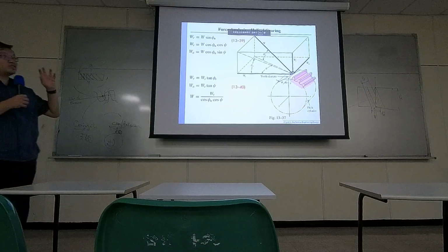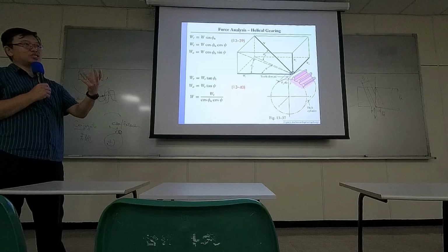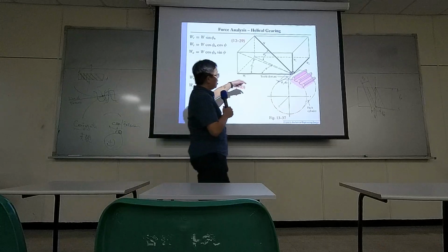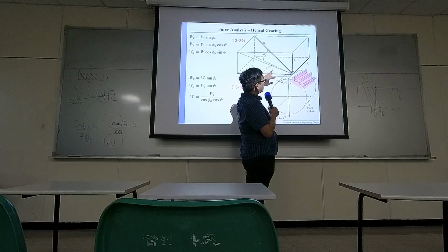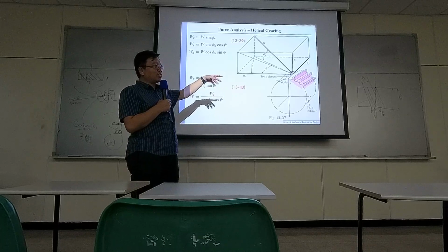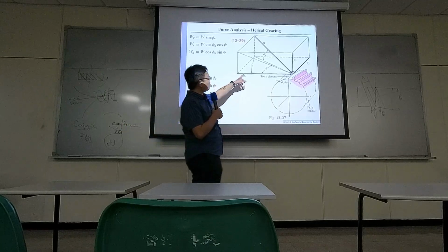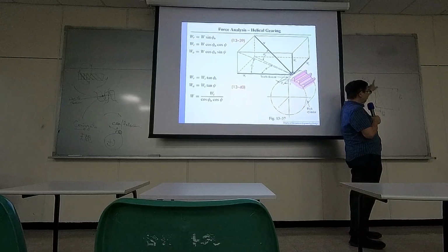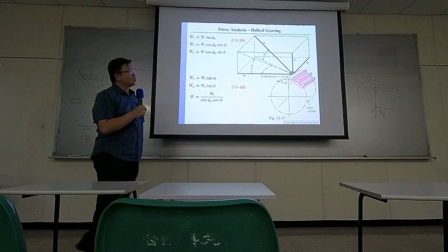So this is exactly why we need to know about pitches along three different directions. Because later on, when we figure out the forces from one side to the other, there will be three different force components between the pinion and the gear, and they follow those angles. The angles are, of course, related to the profile of this helical curve.